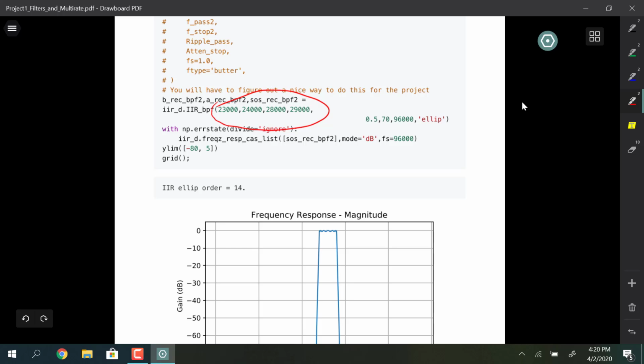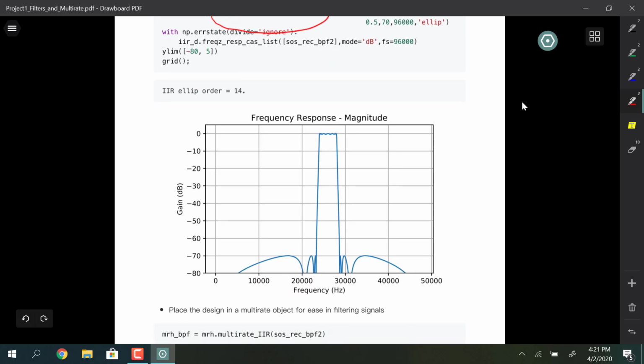So you'll have a shift factor put in there to move it relative to a frequency number that arrives from the outside, or from your receiver. You'll have an FC that drops in there, and that will design this bandpass filter for you.